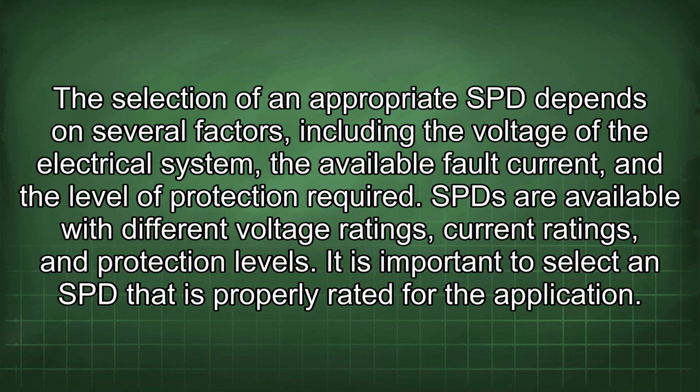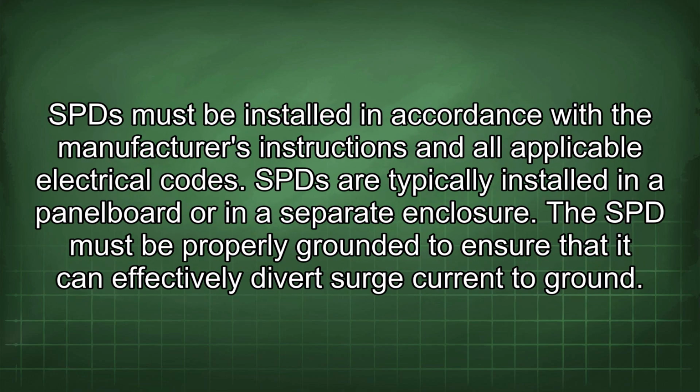The selection of an appropriate SPD depends on several factors, including the voltage of the electrical system, the available fault current, and the level of protection required. SPD are available with different voltage ratings, current ratings, and protection levels. It is important to select an SPD that is properly rated for the application. SPD must be installed in accordance with the manufacturer's instructions and all applicable electrical codes.